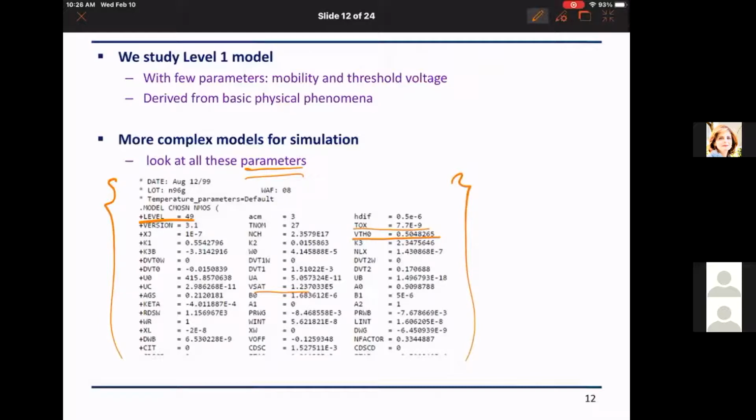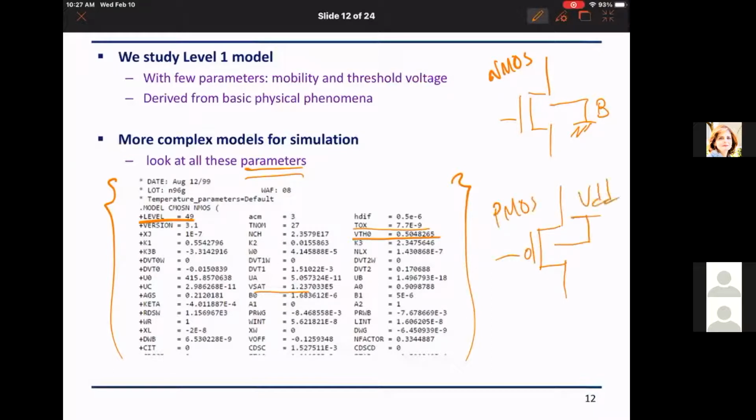Okay, so yes. If the MOSFET has 3 pins, where is the body connected? Okay, so when we have 3 pins for the MOSFET, we said for the NMOS, we will always assume that the body is grounded, and for the PMOS, we will assume that the body is connected to VDD. Yes, but as an electronic component sometimes they come with 3 pins.